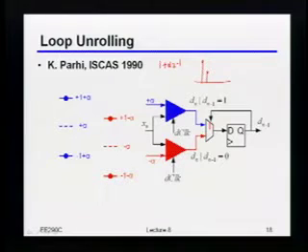Okay? So just to clarify what these diagrams are showing you, if you have a channel that looks like this, where the main tap is just 1, and the second tap, or the post-cursor tap, is alpha, that's basically saying that there are 4 possible levels you can get, right? Because even though my main thing is plus or minus 1, I'm always going to get a plus or minus alpha from the previous bit. In other words, with 2 bits, there are 4 possible combinations you can get, okay?